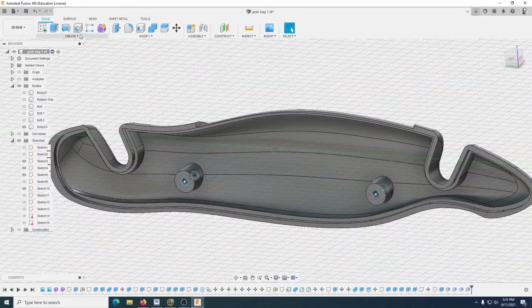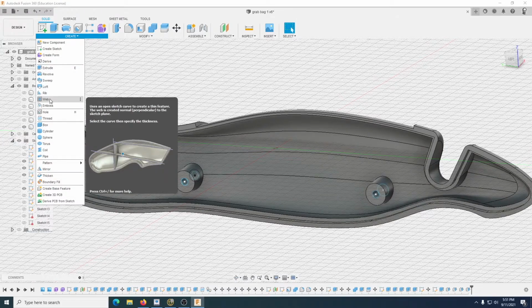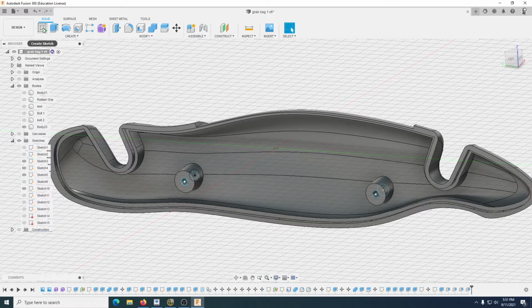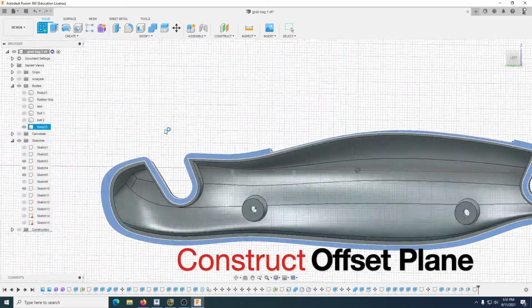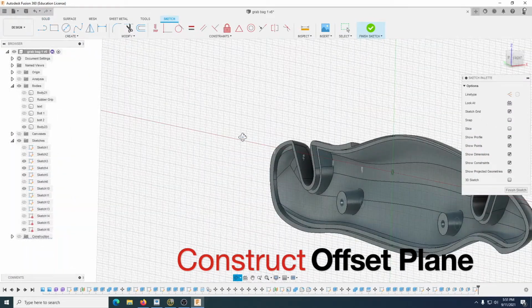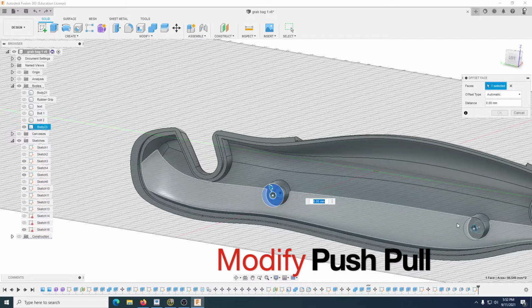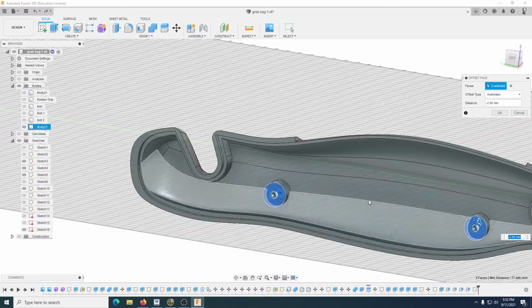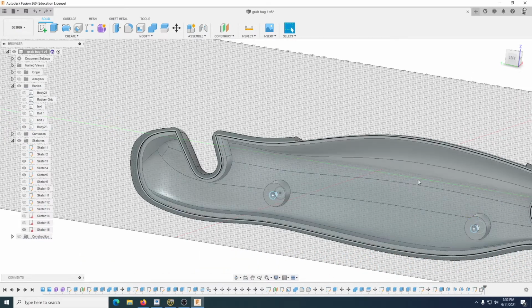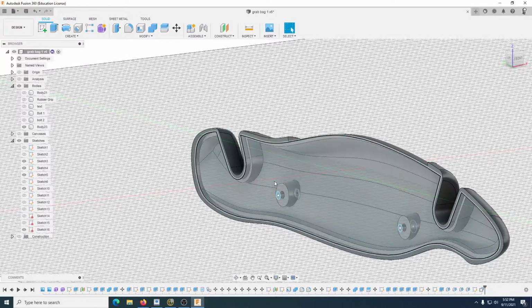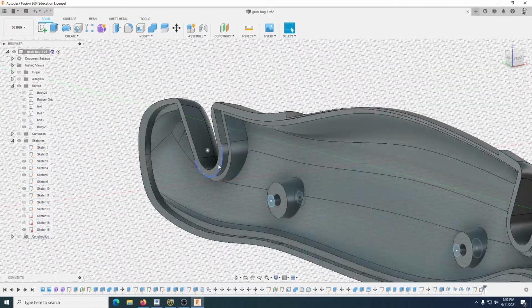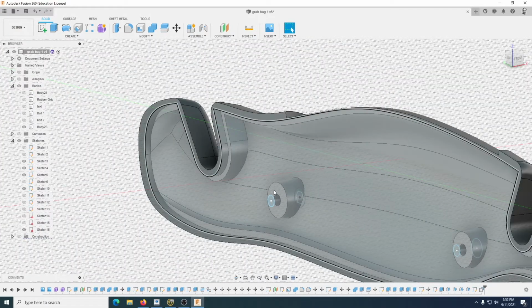To do that, go create, and we're going to go to web. But first, we need to draw some lines as to where we want those webs to be. Pull that one. 1, 2. Click that, so it reduces it down, and OK. By push pull, it follows the draft angle. By clicking this side here, it then pushed it to that.